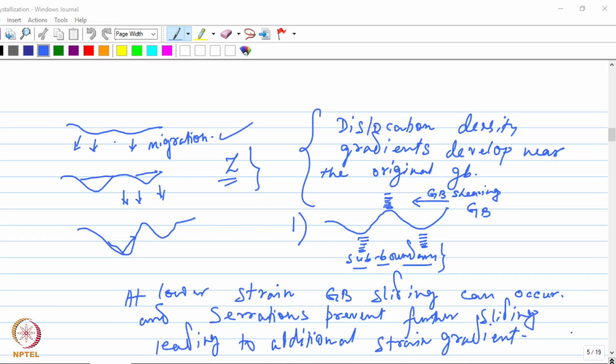So to summarize these two forms of dynamic recrystallization, DDRX and CDRX, we can say that the DDRX process occurs in conditions when dislocations can accumulate to generate a gradient in dislocation density or strain energy across the grain boundaries to form the nucleus. Okay.